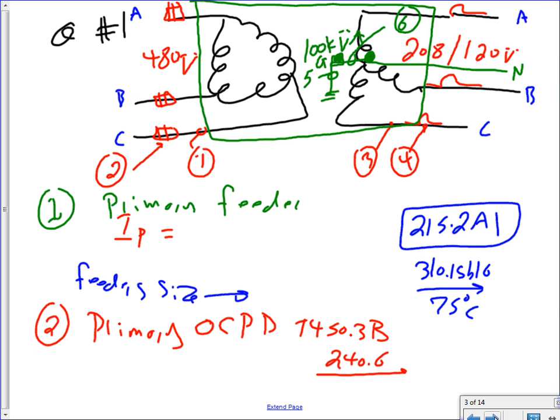Now, I have two examples, I believe, here. Remember, this is the power system. Now, we talked to Excel, and we decided for our building, the building that you guys have, we need a transformer of 100 kVA, right? Our transformer was 225, if you remember. This is a 100 kVA transformer, and I decided in conjunction with Excel that my building is going to take 208/120, three-phase system, Y grounded, and the transformer is 100 kVA.